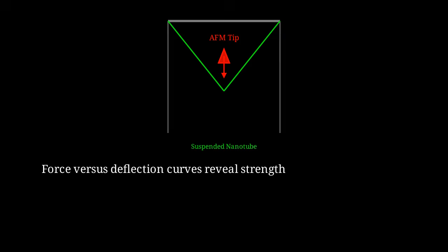The force versus deflection curve reveals elastic modulus and breaking strength. Changes in these curves before and after adsorbate exposure quantify the effect. Advanced AFM can even image individual adsorbate molecules, allowing direct correlation between adsorbate position and fracture initiation site.